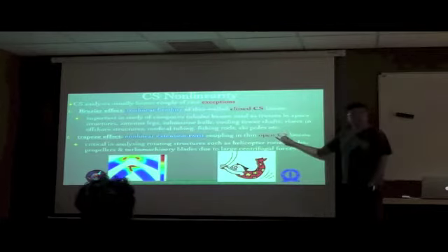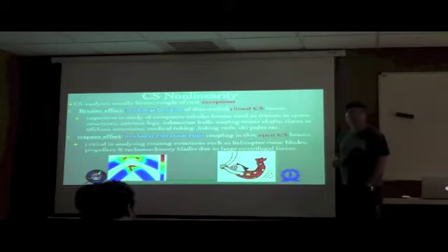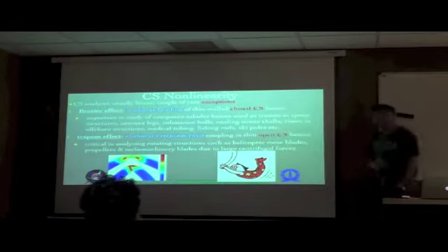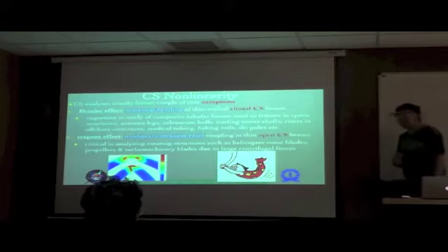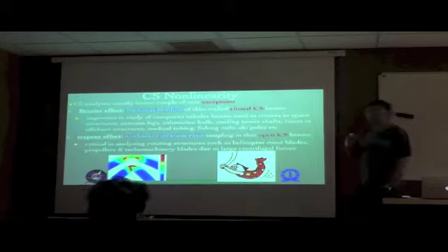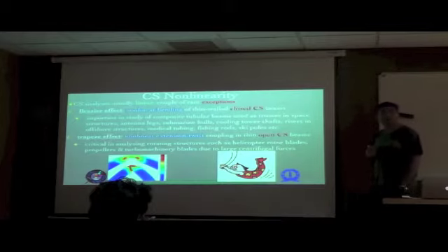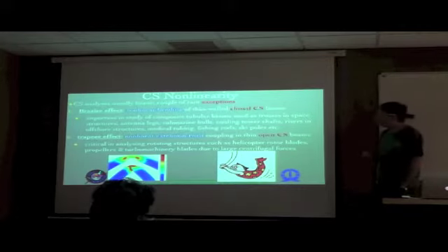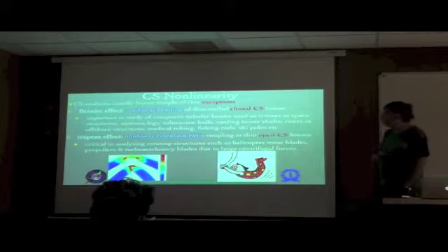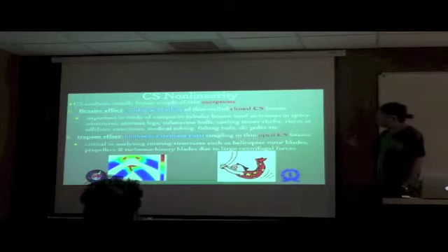and where the cross section of the one-dimensional structure is an open section. So some examples of those are, for example, rotating structures. We have been discussing over and again the helicopter rotor blades. So helicopter rotor blades, especially the flex beam part which is in the yoke, and or the entire helicopter rotor blade itself, including the airfoil cross section that you have. This can be considered as an open cross section beam with thin walls, because typically the airfoil cross sections which are used there are not very thick, so the maximum thickness to chord ratios are of the order of 10% at the most, which basically means that they are in this particular category.